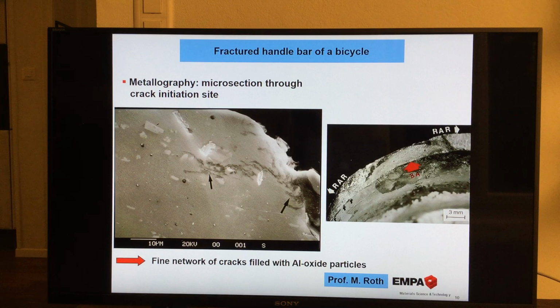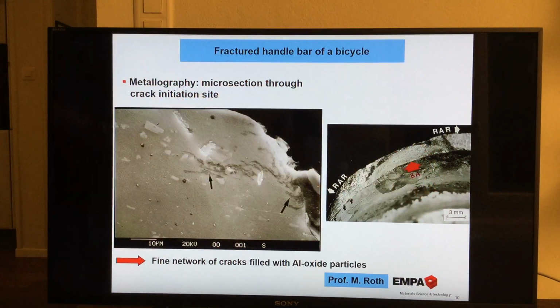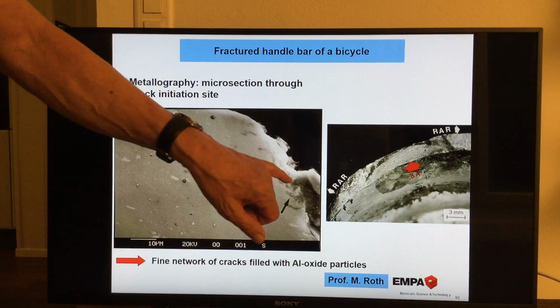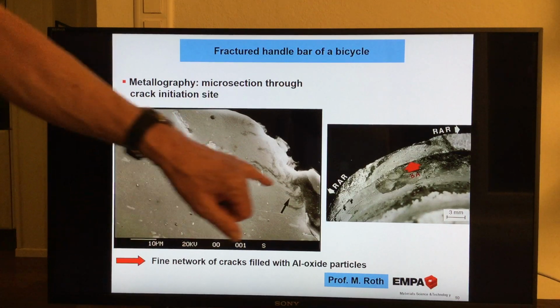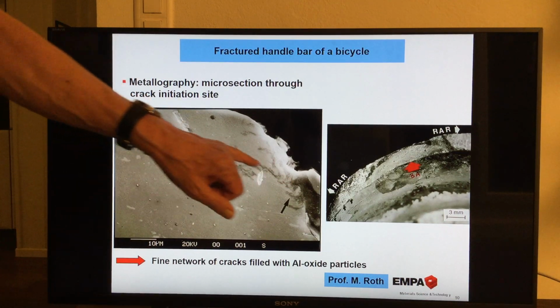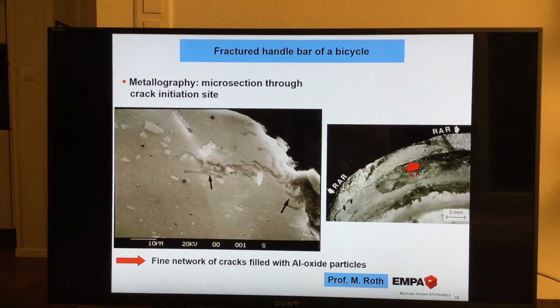However, due to that movement, it's clear that the aluminium oxide layer which is here was destroyed. And hard aluminium oxide, you know, is like a grinding material, it's a ceramic material, extremely hard, and of course it will be embedded in the pure aluminium inside. And this is the start of a crack. That's the start of the crack. So we have here the key of our failure already.